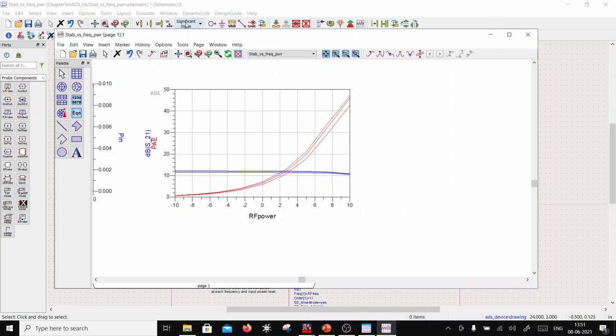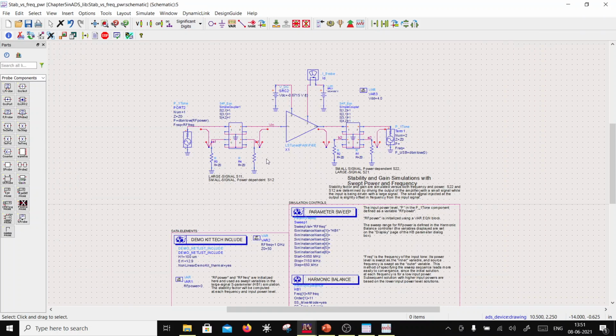Okay, so what I want to do is at this output power, I want to see how much is the load pull effect. Now, here the load pull has to be done at a constant output power. So basically the gain has to be bumped up so that it delivers the same power. Otherwise efficiency has no meaning. It has to be specified at a given output power, not a given input power, right? So let's see how in the example a load pull is implemented.